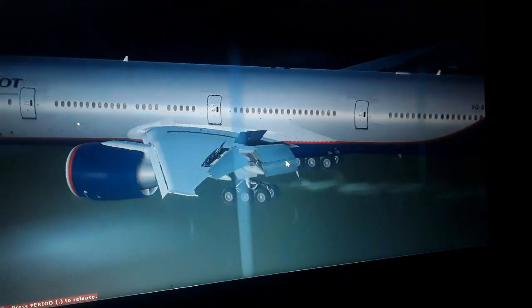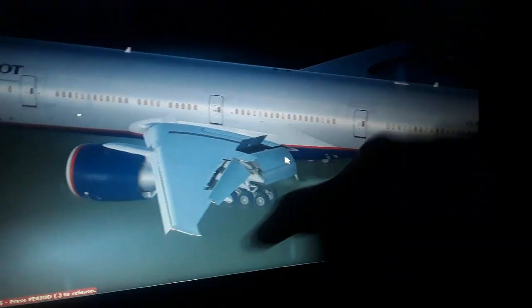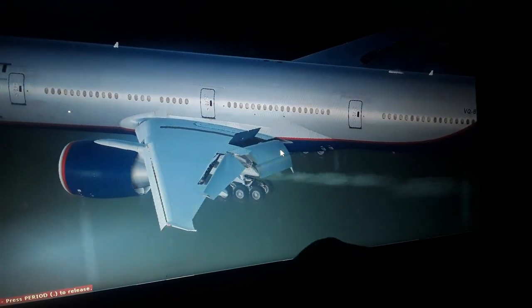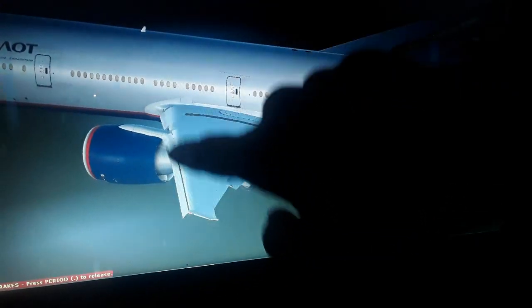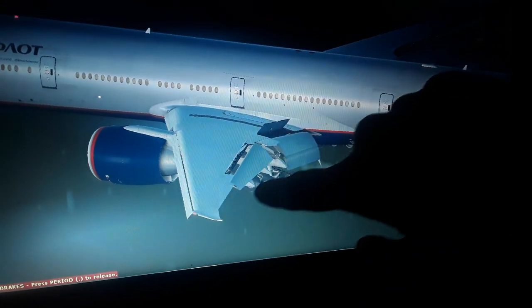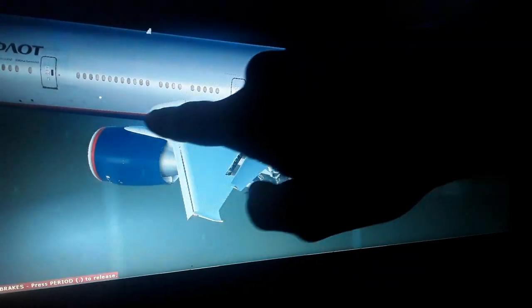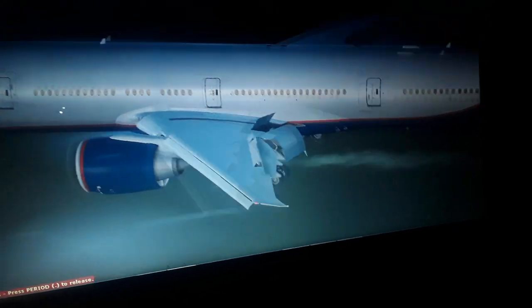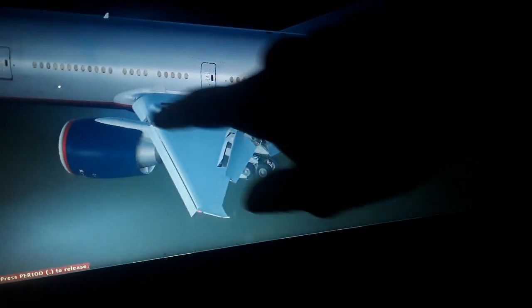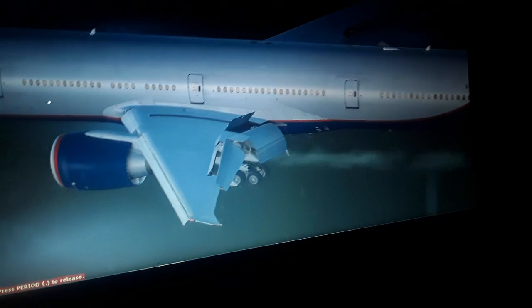Also, you can see the top surface of the wings. It has more curvature above the wing. So the airflow of the air mass as the aircraft accelerates to the takeoff speed, from the leading edge all the way back to the trailing edge, is moving faster above the wing, the stream of air. So we have lower air pressure above the wing using the Bernoulli theory.